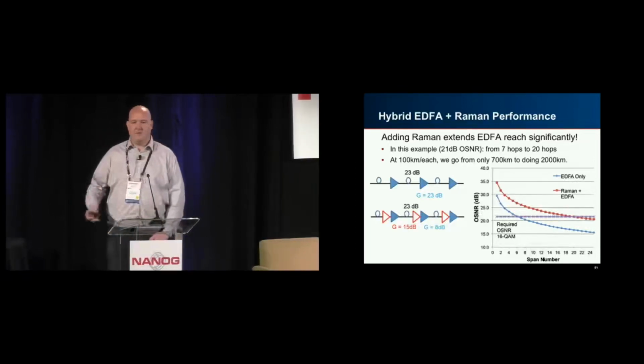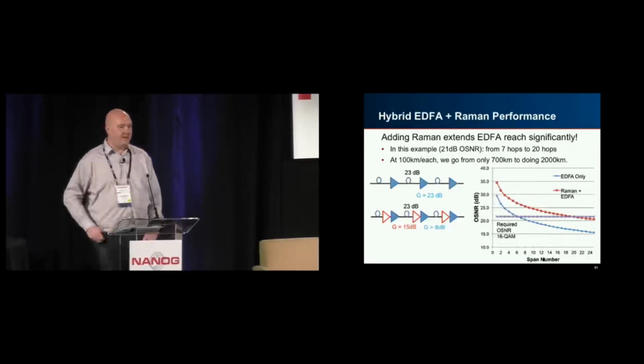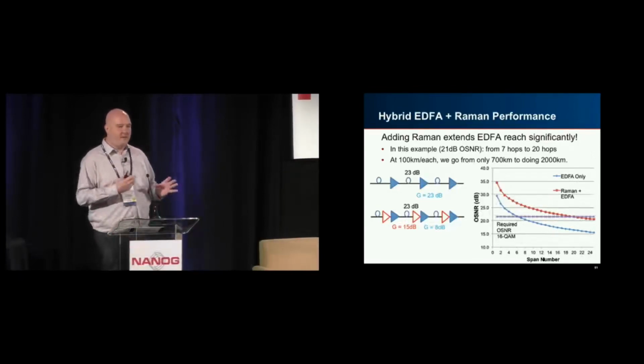And in fact, you can probably do better because this is assuming a very, very high OSNR, and technology has actually gotten quite a bit better. But you see here, because you were able to amplify the signal with the Raman, you no longer need as much gain on the EDFA when you send it, and you've kept that higher OSNR.